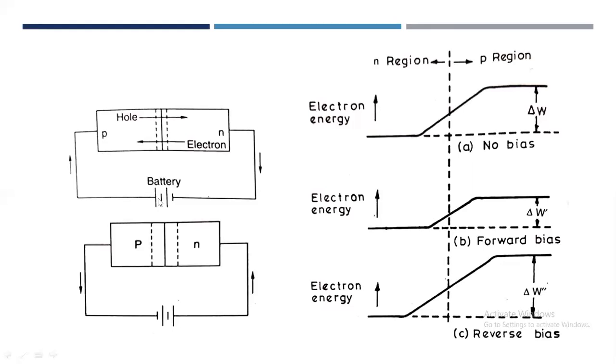As you can see in this figure, a battery is connected across the PN junction. The mobile charges, holes and electrons, get energy from this battery to move. The bias potential exerts a force on holes and free electrons in the P and N material respectively. This opposes the resulting force of the barrier field and causes these carriers to crowd closer to the junction. Obviously, the holes are attracted toward the negative charges and the negative charges toward the positive charges.